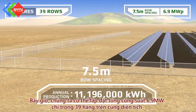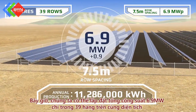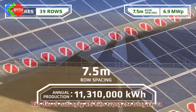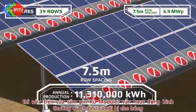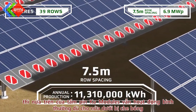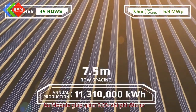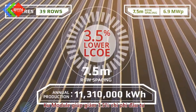Now we can fit 39 rows of modules in the same parcel for 6.9 megawatts total. At the beginning and end of the day when shading occurs, the top halves of the modules are still producing power, even when the bottom halves are partially shaded. Factoring in the additional equipment cost, Ku modules deliver a 3.5% lower LCOE.